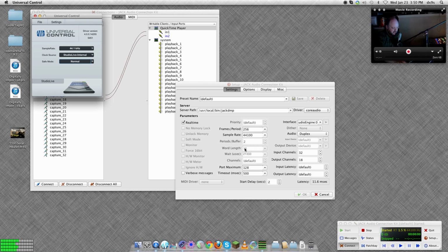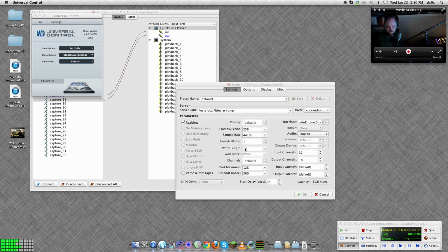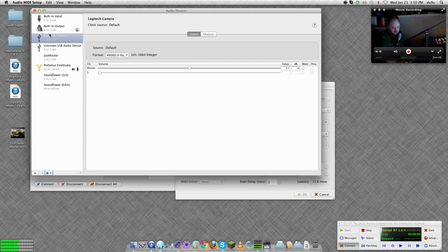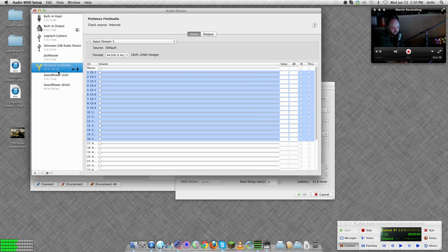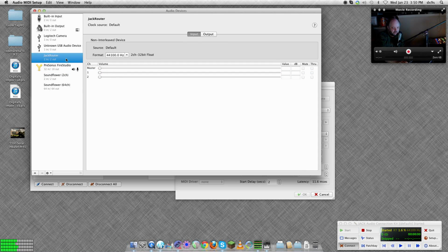And let me bring up audio. So here I happen to have all of my record and playback from the system currently pointing to there, but I could point to any other device, including the Jack router if I wanted to. The thing is that things only show up and go away in the Jack router as they're being used. If there's still a connection being maintained and the program's still loaded in memory, it will remember where it's going, but if it unloads and completely loads up again, you'll have to reconnect what to what.